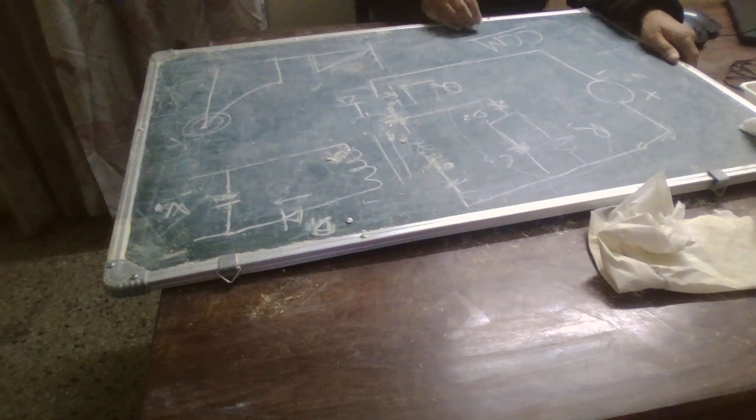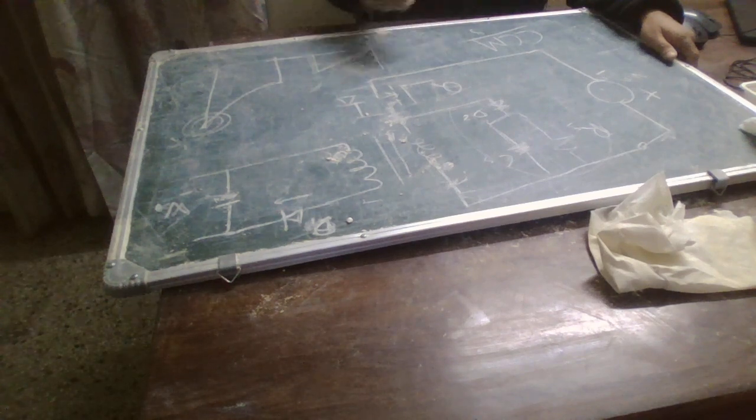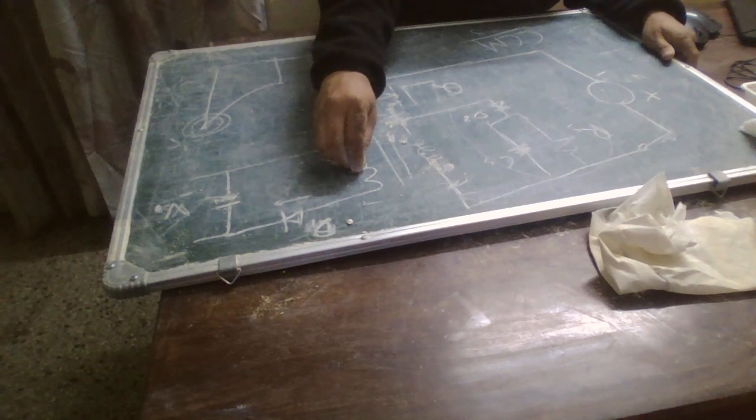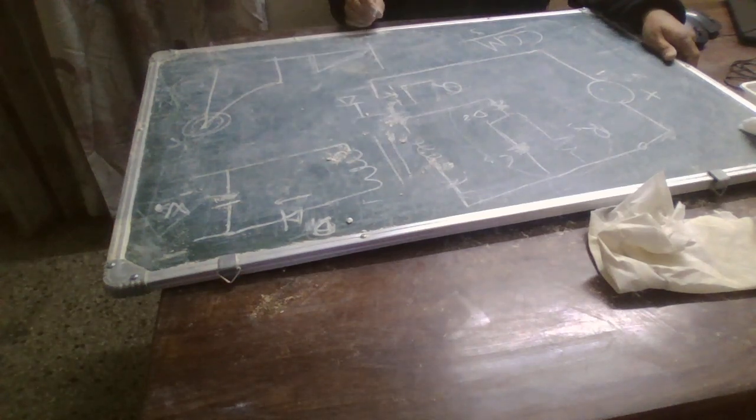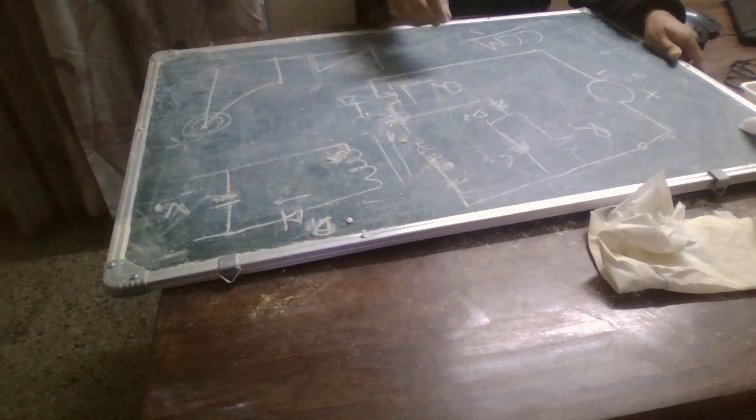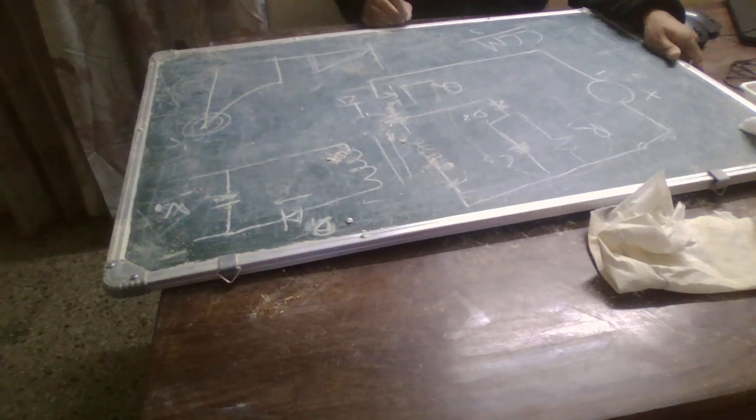So now here we have the concept of secondary reflected voltage, because this voltage gets reflected on the secondary. There is leakage stored energy in the transformer core, and it gets reflected back to the transformer primary. That's what is known as the reflected secondary output voltage. The maximum stress on the switch would therefore have to take this secondary output voltage into account in the equation.